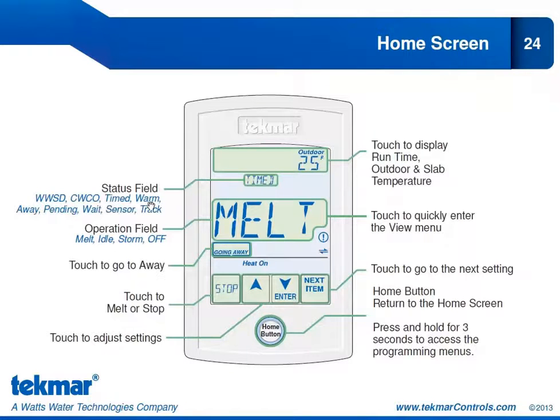Warm, which tells you the slab is currently coming up to melt temperature. Away, if you put it into the away scene. Pending, now this would show if you were in a melt and then the temperature dropped below cold weather cutout, you would see pending on the screen, and it would actually alternate between pending and cold weather cutout to tell you it will return to that melt sequence once the temperature rises above that cold weather cutout. We have the wait, and the wait would show up if we are waiting for that zone to operate due to your priority setting.